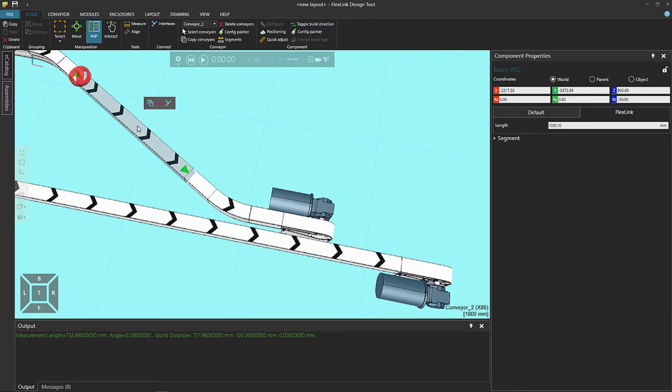Selecting the beam. Extending the beam by adding 41,06 mm. And applying basic trigonometry to create this formula. In this length field we can use expressions, such as plus and minus, but also do trigonometric equations.